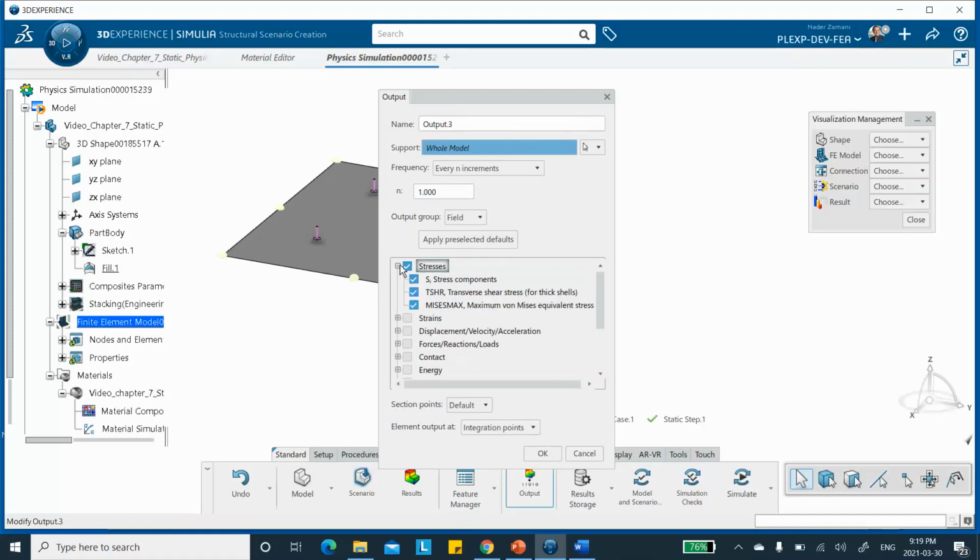Okay. All I want is the stress components. Von Mises is a freebie there. Okay. And then you say, how do you want this? I want it by layer. I want this information to be given to me by layer. And I want it at all three locations, top of the layer, bottom of the layer, and middle of the layer. Because remember, these layers essentially are sheets, lamina. So it has a top, it has a bottom, it has a middle. Okay, so ask for all of them, whatever you want to apply, go ahead and plot. And then you say okay.